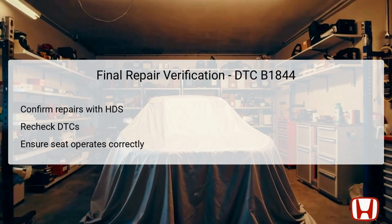Following this, verify that the power seat operates correctly, moving in both forward and backward directions as intended. Proper functionality after repairs reassures the technician that the underlying issue has been resolved and that the vehicle is now safe for use. Always document the findings and any repairs conducted for future reference and maintenance records.